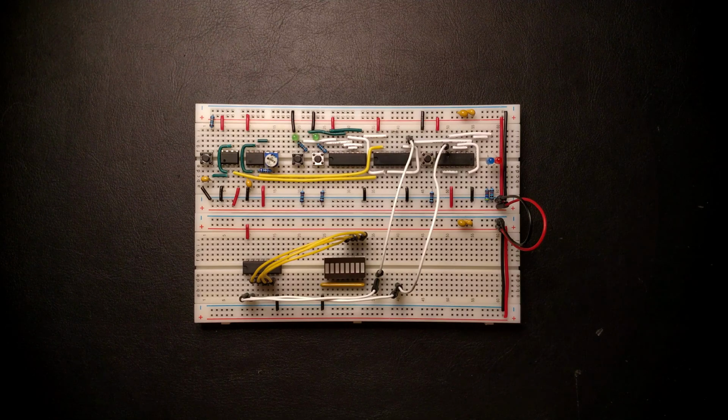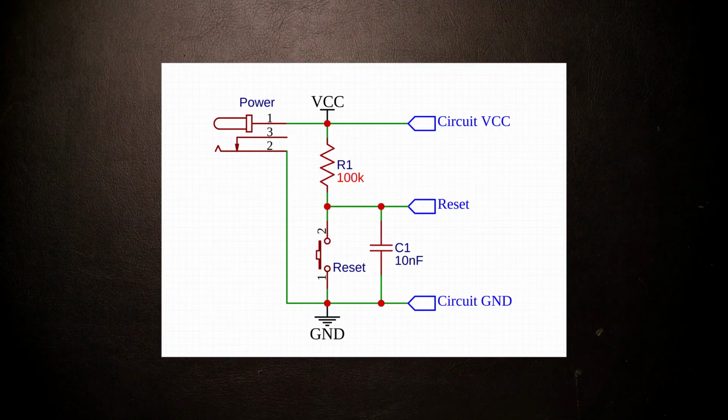So what we need is something that does the same thing as pushing that step mode button and reset button on power up. We can achieve this effect by connecting a small capacitor between the button and ground. The capacitors to ground act like a short circuit because they are fully discharged, effectively tapping the button for us. But then they will quickly charge through the pull-up resistors. And when the circuit is powered down again, the capacitor will slowly discharge itself, through parasitic effects, but also through the rest of the circuit.